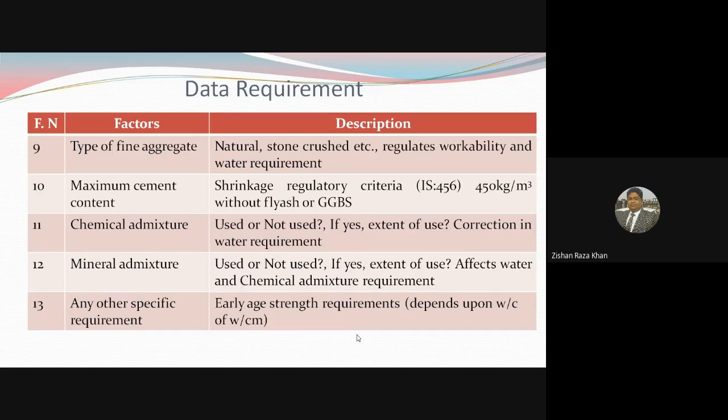Now, chemical admixture. Are you going to use it or not? And if you are going to use it, what is the dose? You need to figure it out, because correction of water requirement will be done based on your dosage and type of admixture.